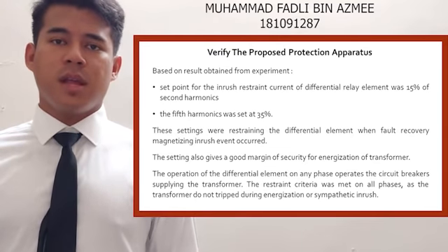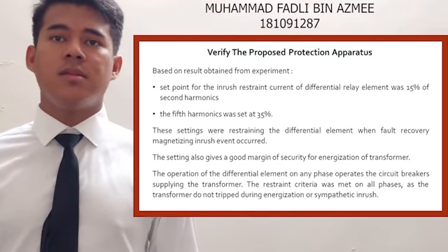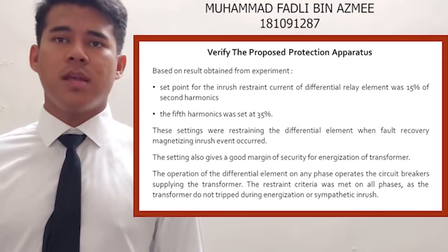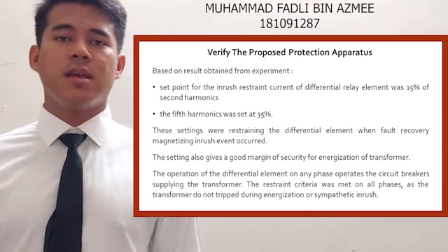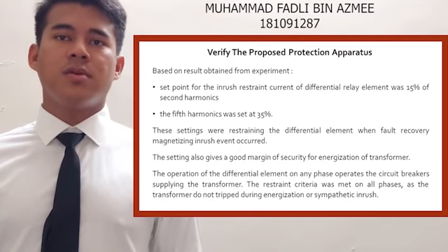The result demonstrates that the differential relay operating current is zero since the total of the current entering its primary restraint winding equals the sum of the current exiting its secondary restraint winding. This means that the protection zone is in perfect working order.